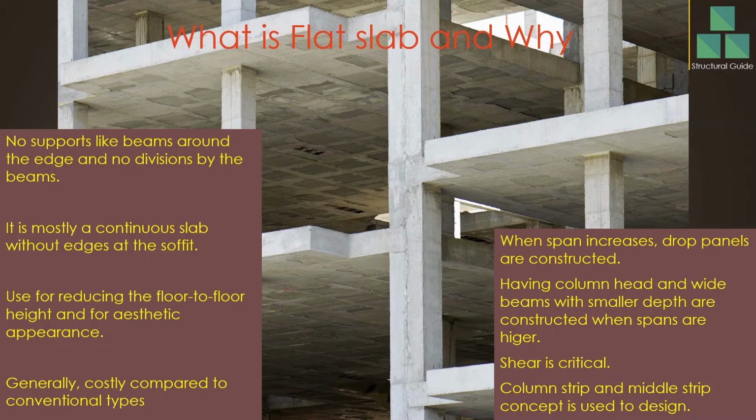It is used to reduce the floor height. We can reduce the floor height because the beam space is not needed. Generally it is costly when compared to conventional slabs because it doesn't have supports like beams, therefore we have to increase the thickness. When the span increases, drop panels may be required. Column heads and wider beams with smaller depth are constructed when the span is high.